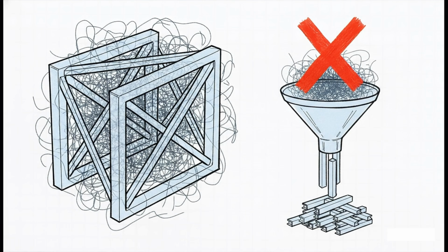Oh, and watch out for the not or negate condition. This is an absolute game changer for fine-tuning. You know when a structural model imports with a bunch of random 2D model lines that just clutter up your 3D view? You can set a condition that finds everything in the structural model, but then use the negate function to basically say, not lines. It's an incredibly powerful pro tip to instantly clean up those bulk searches.